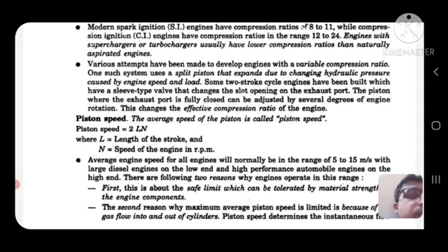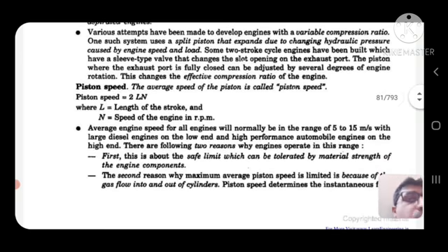In the engine, the slot opening on the exhaust port, the piston position where the exhaust port is fully closed, can be adjusted by several degrees of engine rotation. This changes the compression ratio of the engine.